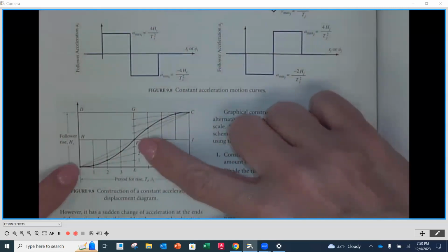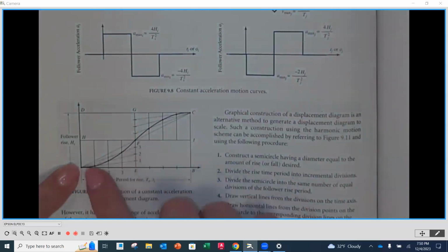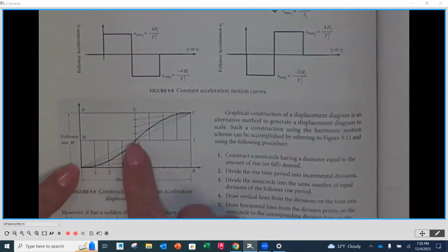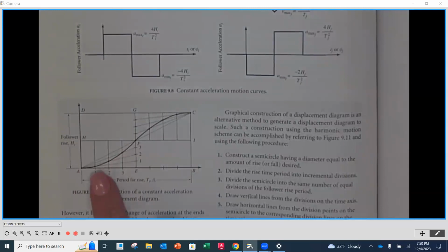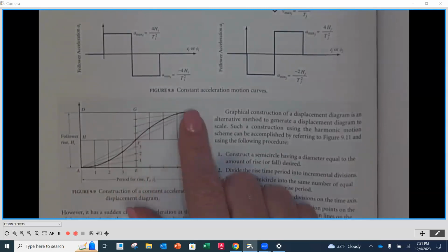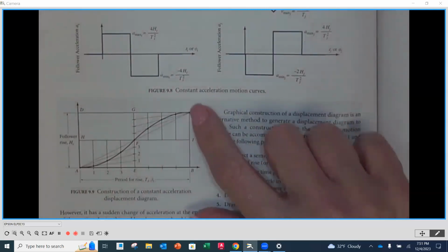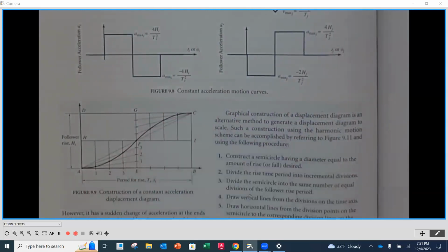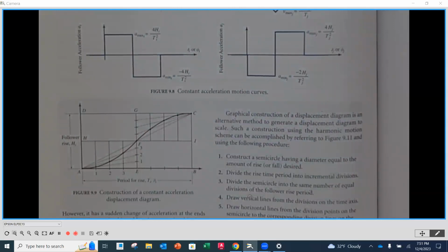And from the vertex A here, you are going to put the lines across. And then you're going to correspond to each one of the 4 evenly spaced sections. And then you're going to do the very same thing on the other side of the curve, starting with point C here going out. And then through those points that occur on those divisions, you're then going to put a best fit spline through those. Okay, so you can imagine in AutoCAD how to do that.